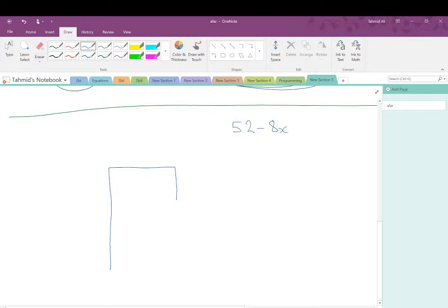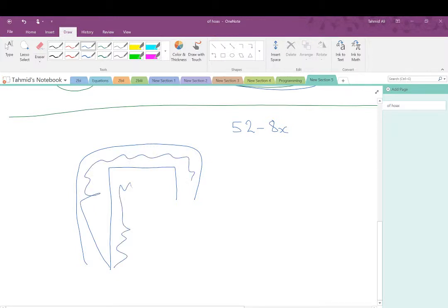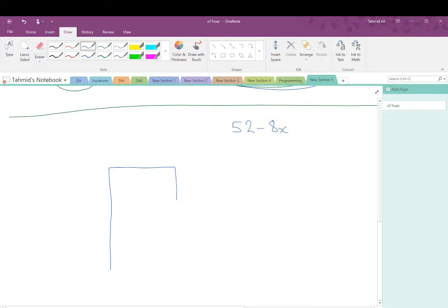You basically have to make an assumption about which way is positive and which way is negative. So I'm going to see positive as the outer parts of the frame. All the bending moments acting here are going to be positive, and any bending moment happening inside the frame I'm going to consider negative, just so everything is consistent.